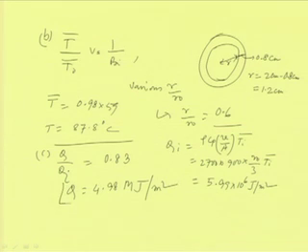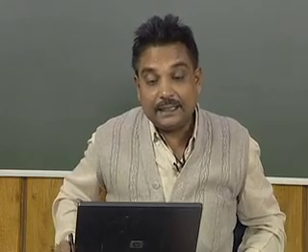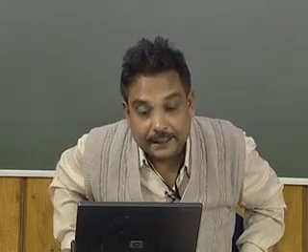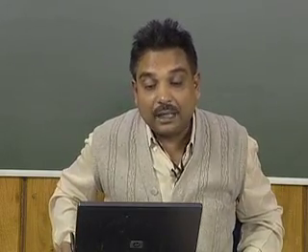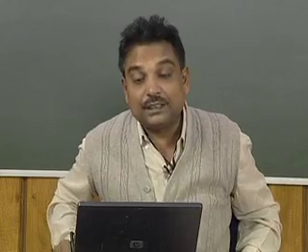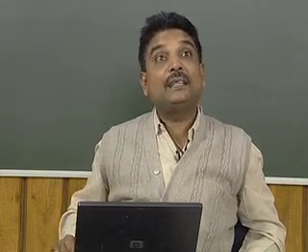So, we see that this is the heat loss from the spherical system, and from the spherical body the heat loss is about 83% of the original heat content, the initial internal energy content. 83% of that is getting lost in 1 minute. So, heat loss from the spherical body is the maximum per unit area. Everything we are discussing is per unit area.